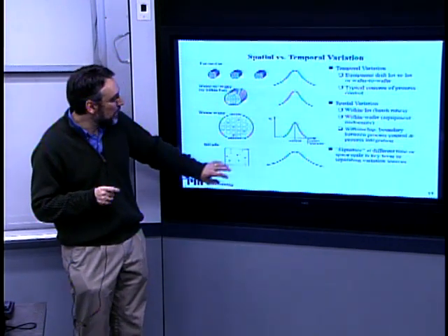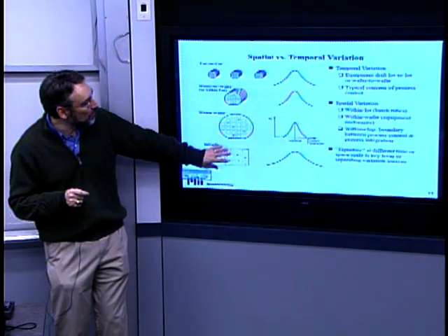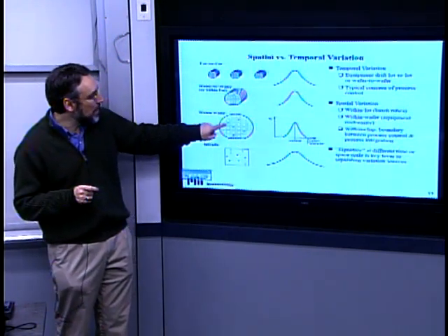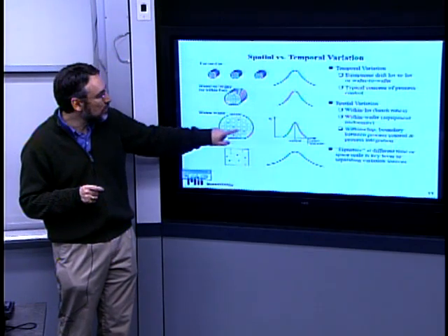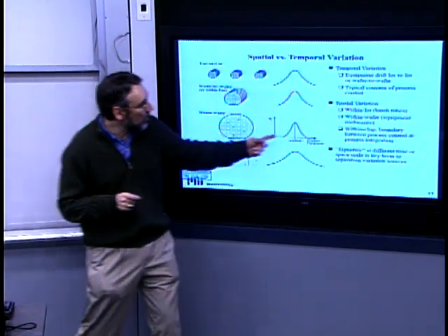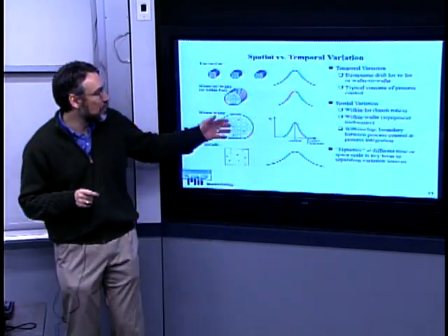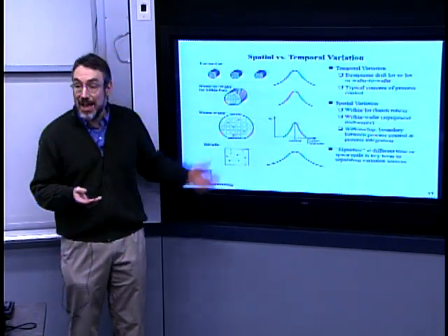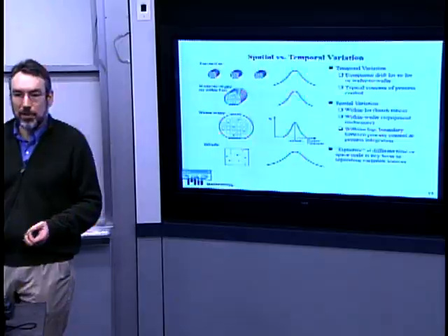Now what's interesting is we have a physical nesting. On the wafer we have many chips. Now if I were to take and measure the same transistor on each chip, I would also get a distribution. I have chip-to-chip variability in parameters. And often that will come because of different physical causes.